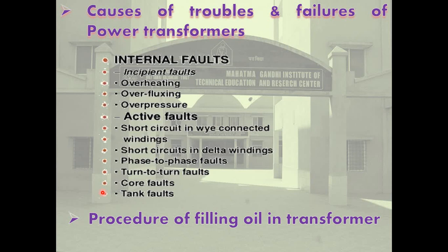Now filtering process and filtering plant for transformer oil filtration. The oil purifying equipment removes the following from the oil: dissolved moisture or free water, solid particles. The oil purifier has the following components: first is vacuum tank and vacuum pump, centrifugal plant, oil pump, heater, valves, temperature gauges, vacuum gauges, pressure gauges, vacuum chamber, strainer filter, and streamline purifier.